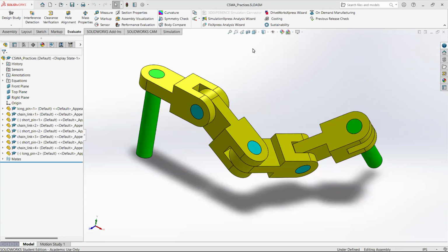In this video, we're going to talk about configurations as they pertain to assemblies. So we did a video on configurations in parts, which is incredibly useful, and assembly configurations work a lot the same way, but they have a lot more practical application. Because in assembly configurations, much like in the part configurations, where we can disable features, in the assembly configuration, we can disable entire components and have an entirely different setup of parts.